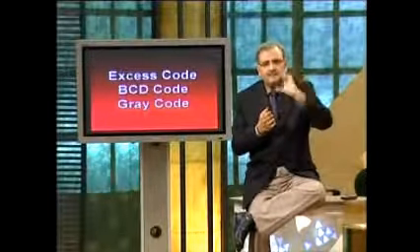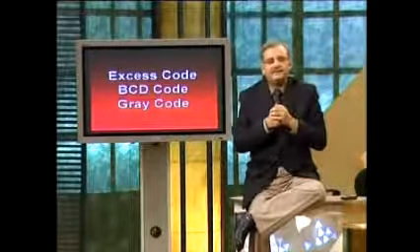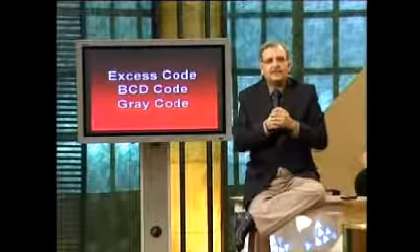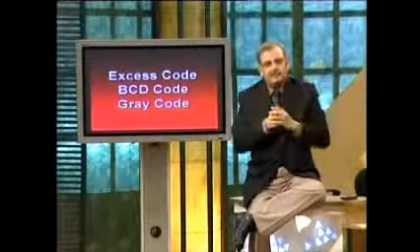So, it would have been better if -1 had been represented by bits 0, 0, 0 had been represented by bits 0, 1 and positive 1 had been represented by 1, 0. So you have a smooth scale through which you can compare. So 0, 0 is of course less than 0, 1, which is in fact a 0. So the excess code is used to give a uniform scale to positive numbers and negative numbers.